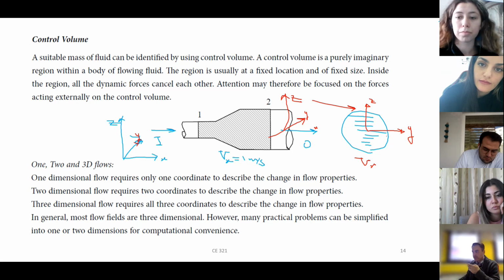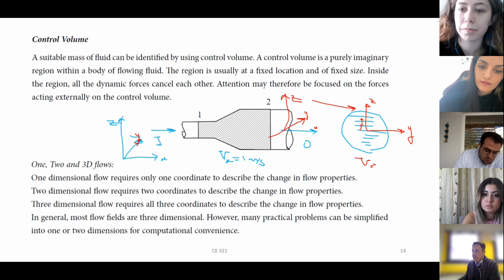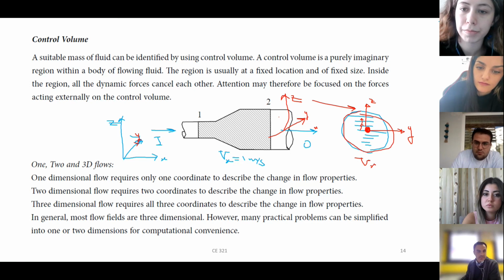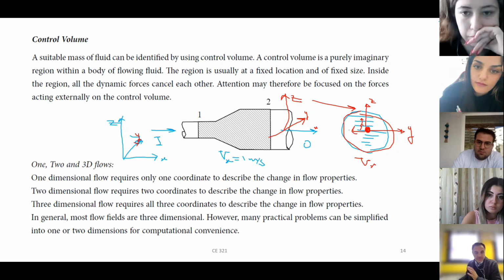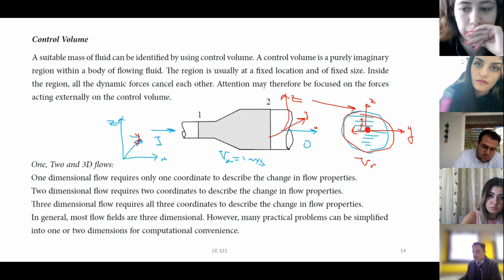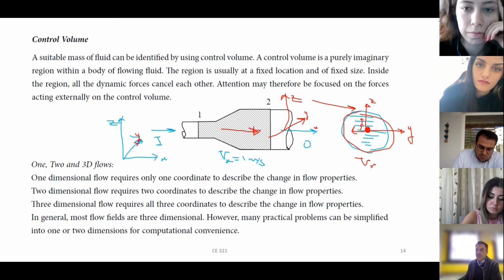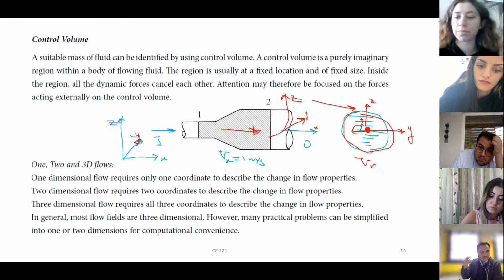What comes to you in this section. However, water velocity can also vary in this direction. You know that the maximum water velocity is at the middle, because at the wall the velocity is always 0, the non-slip condition, you remember? Therefore, in the y direction or z direction, the water velocity varies. But you neglect that. You just gave me Vx as one direction, which is the average velocity in the x direction, and this is called one-dimensional.